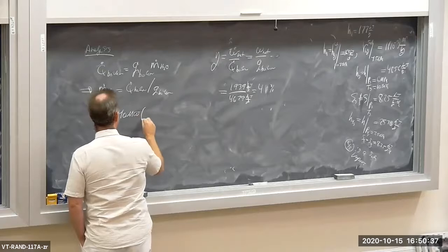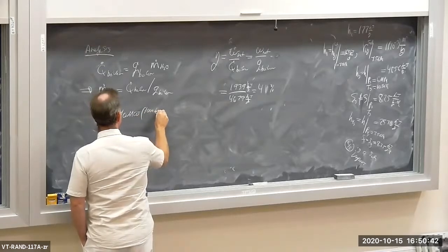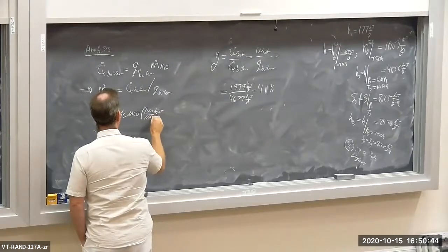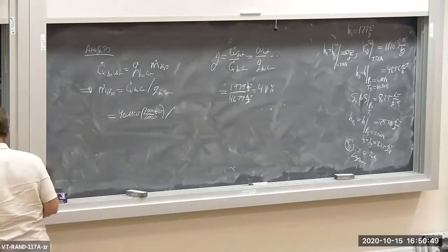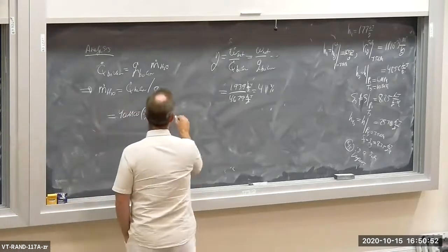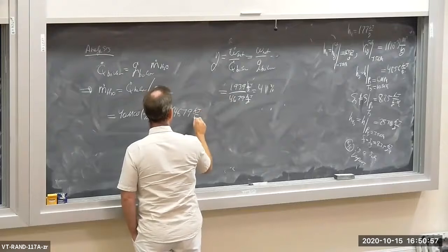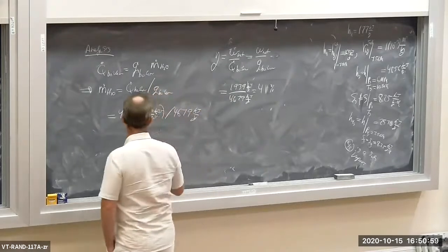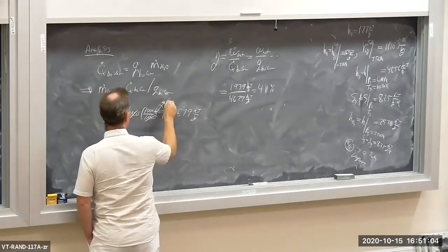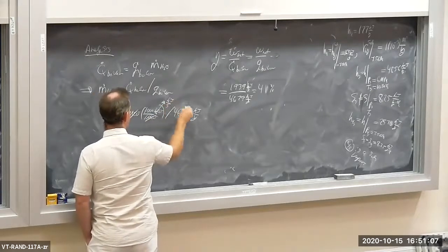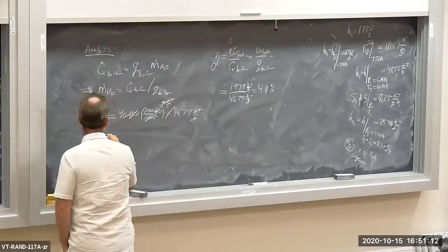I'm going to have to convert that into kilowatts, so that's 1,000 kilowatts per megawatt. And then I'm going to divide that by the specific heat addition of the boiler, which is 4679 kilojoules per kilogram. Again, the megawatts cancel, and a kilowatt is a kilojoule per second. The kilojoules cancel out, and I get kilogram per second, which is exactly what I want.